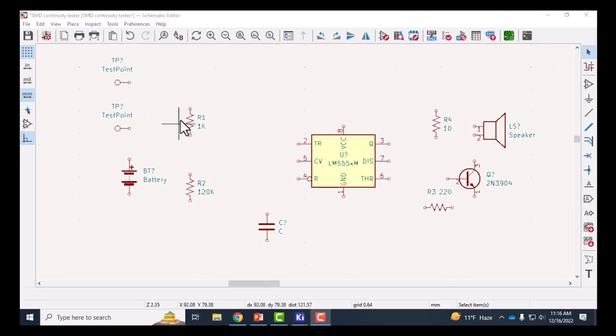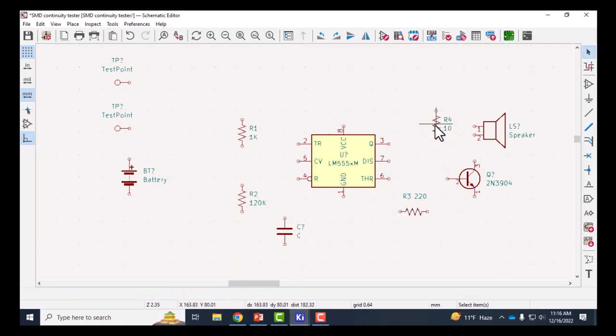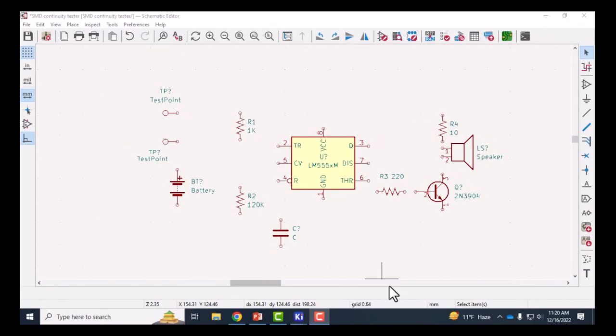Before I connect the wires, I'm going to move some of these components. So I've highlighted both of those at the same time, and then I can drag them. Another way to move symbols is just hover over it and hit the key M on the computer. That's a hotkey for move. So I can move these symbols to anywhere on the board I want and then click to release them. So now that I've moved components around and got them where I want them, I will start connecting the wires.